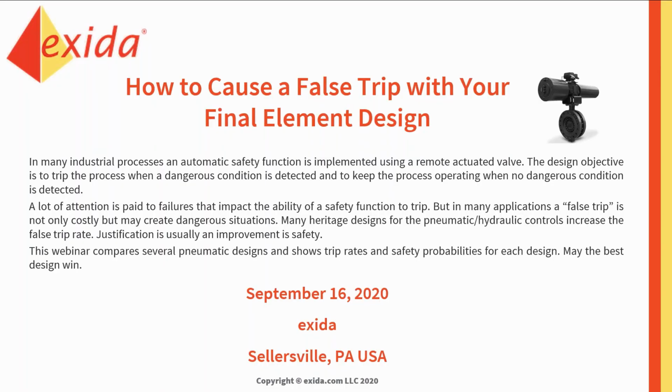Many of the heritage designs out there have pneumatic or hydraulic controls, and they actually are increasing the false trip rate. Oftentimes, the justification for that increase of the false trip rate is because we're working on improving safety. Yes, absolutely, if you put redundancy in your system, you are going to improve safety. But at what cost? Usually, it's the high cost of a high false trip rate. And that's not what functional safety was put in place to do.